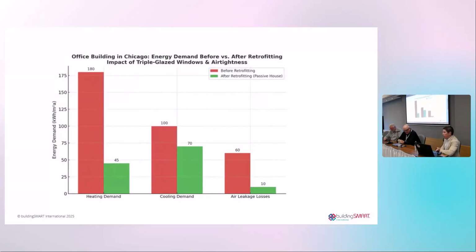You can see we use passive windows, so it means it's a huge step towards energy efficiency and improvement, before retrofitting and after retrofitting. You can see why it's such a big impact. The window itself is a triple glazed window with insulated frames. We had leaky windows before, right? In the previous case, we had leaky windows without frame insulation, and draft, or air leakage.